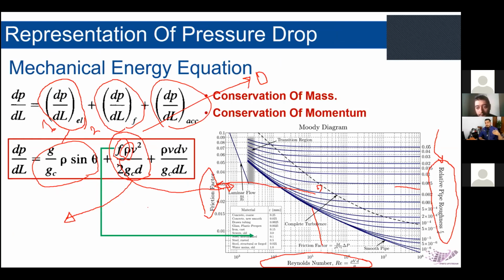The only thing you will change in the model is the wellhead pressure, and you will get different flow rates depending on the operating condition, because the water is incompressible and there is no gas to it. The only thing you need to know is the density of it and how much salt and how much equivalent solid it has. So this is the first route, and this is the easiest one because you already have the well test.